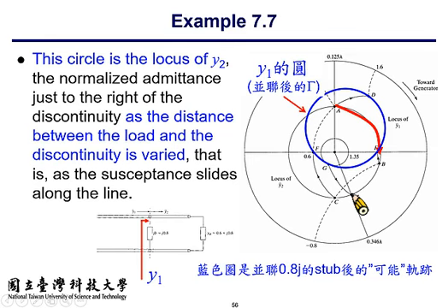So by connecting the shunt components of point A at the position H, you will move to the new position at the position G, and then if you connect another transmission line at the position G, the magnitude of the reflection coefficient is merely, the standing wave ratio at this circle is merely 1.35, which is relatively good in terms of standing wave ratio. Okay.